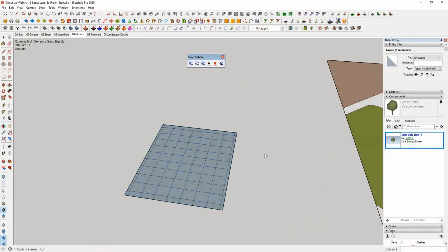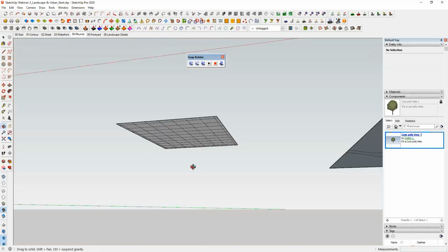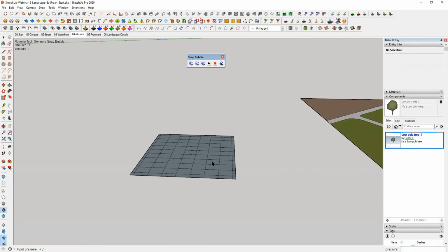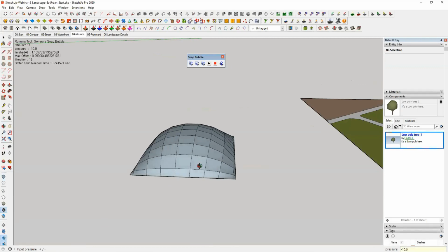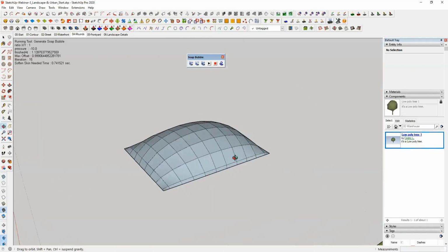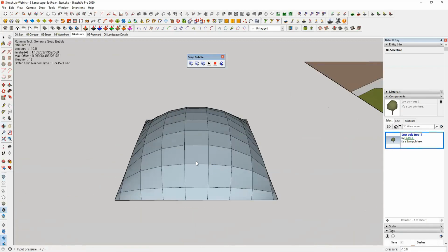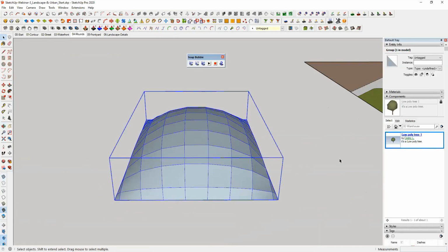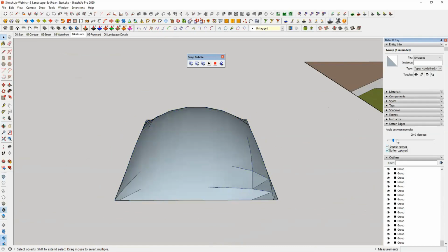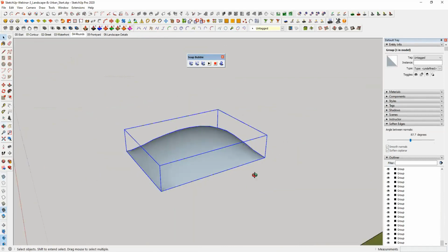Click on the bubble. Okay, and again we have the negative face upward and the positive face downward, right? So in order to create the bubble along the negative face, I'm going to type in the negative pressure, negative 10, enter. The pressure will inflate the bubble, right? So we have the mound kind of effect here. Now we can smoothen this further, right? So we can go to soften edges and soften the edge of the bubble, right?